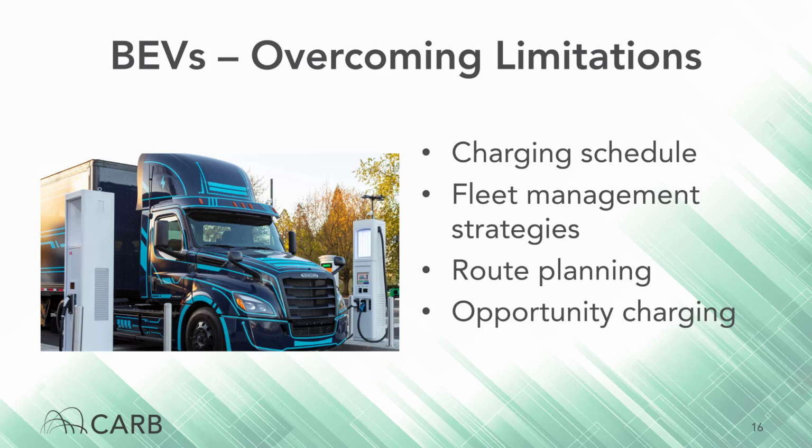Taking advantage of opportunity charging can help maximize how much charge a vehicle will have by taking advantage of any downtime. Charging while loading or unloading a box van, for example, is an excellent way to take advantage of opportunity charging. Remember that there are many differences and approaches to BEVs. Having full batteries is not always the goal the way having a full tank of diesel might be.